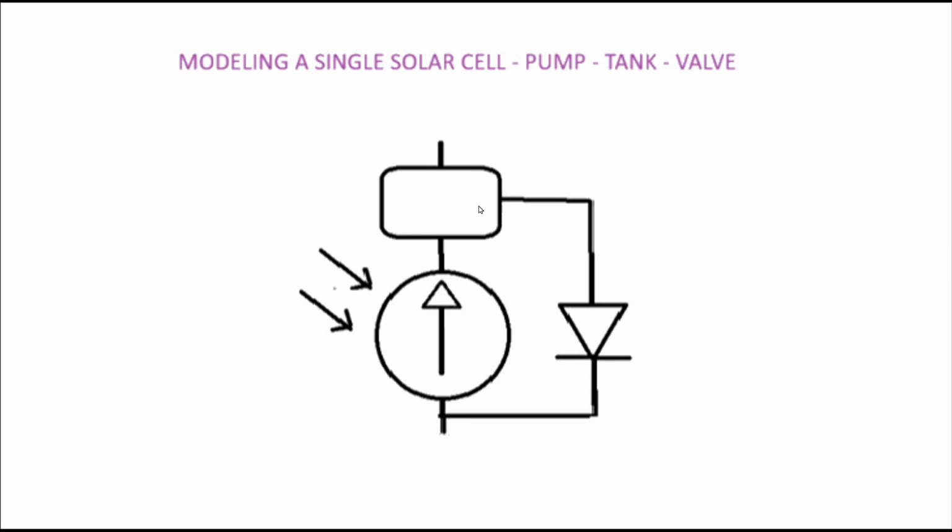So here we're adding a one-way valve that can only flow down in this direction, and the thing about this valve is it opens only at pressures above, say, 5 units of pressure. So at 5 units of pressure, it's going to allow flow.